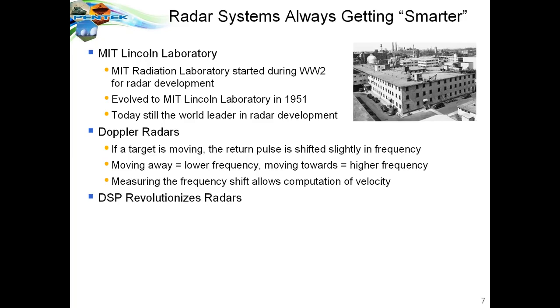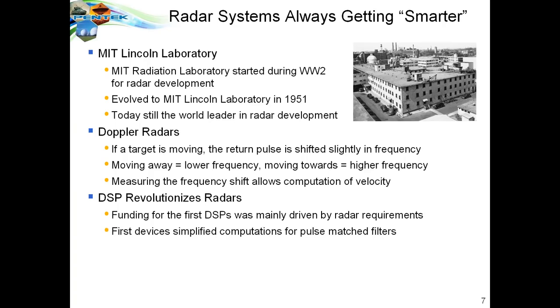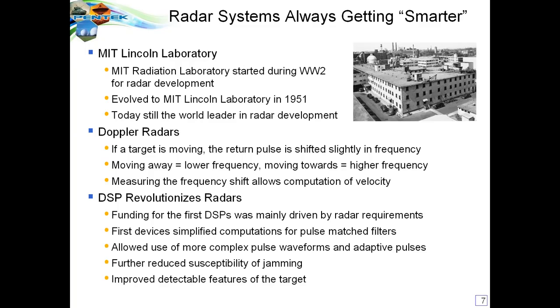DSP has really revolutionized radars. In fact, funding for the first DSPs was mainly driven by radar requirements. The first devices really simplified the intense computations for pulse-matched filters, and allowed the use of more complicated pulse waveforms and adaptive pulses to reduce susceptibility to jamming and improve the detectable features of the target: size, shape, and so forth.